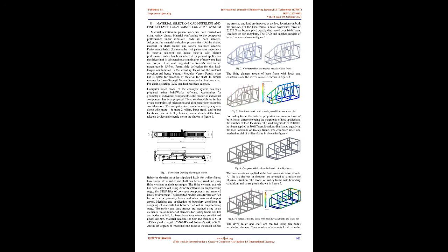Overall length of the assembly is 7,000 mm and the load carrying capacity is 2,000 kg. Self-weight of the entire conveyor assembly is 2,224 kg. The conveyor is powered with the use of a chain drive mechanism wherein the sprockets are mounted on both the ends and are coupled with a single continuous roller chain. Sorting operation of farm yield, i.e., tomatoes, occurs with respect to their sizes.